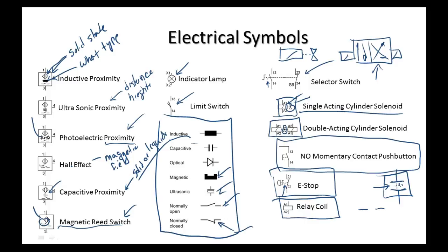And that's the way it does it. It changes the dielectric constant. If we've got time, we'll go over there and look at that. I can take two wires and put them together, just like this, and put AC on them, and put a scope on there, and put a resistor in there, and I can take a plastic bottle and you'll see the output change. I can take a piece of metal and put it on there, and you can literally see the output of the capacitor change depending on what I use as an insulator, which is pretty neat.